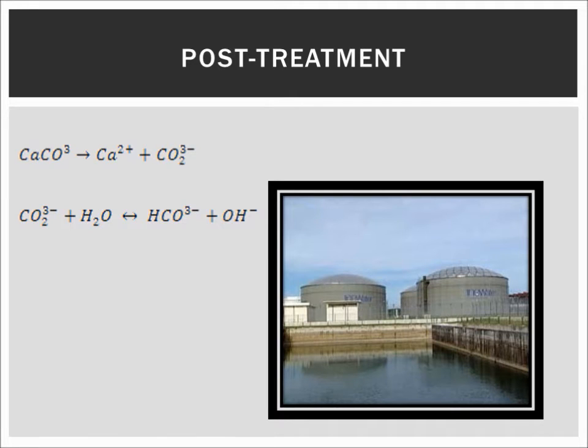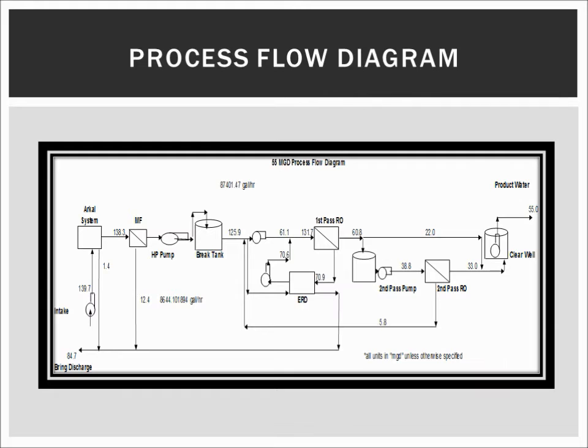The purpose of post-treatment is to prepare the water for distribution after filtration. Although reverse osmosis is an effective barrier to pathogens, post-treatment provides secondary protection against compromised membranes and downstream problems. Because of the water pH and the salt content after RO, it is not adequate for human consumption, and it is necessary to add calcium hydroxide to adjust the pH. To avoid post-contamination during storage of water, sodium hypochlorite is added. Thus, the 3 parameters considered in post-treatment are remineralization, pH adjustment, and disinfection.